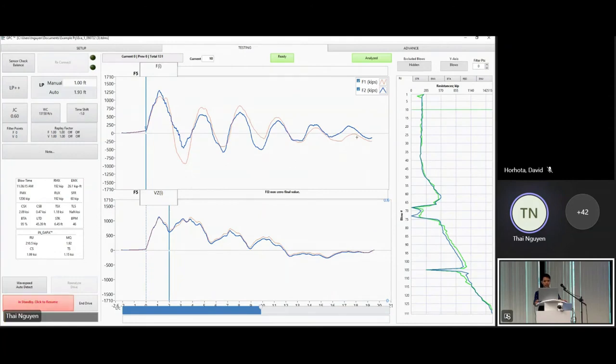In this case, F is not 0 yet because the pile is still in motion. If you see this on a soft drive and want to be very accurate, you might want to lengthen your post trigger length. The post trigger length here is not long enough in this case.